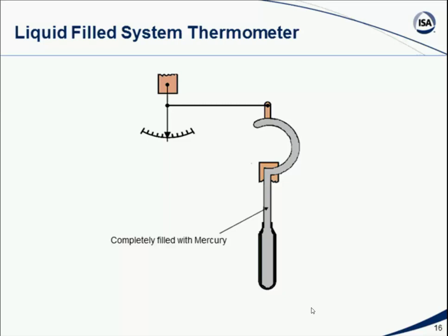Now, that C-tube design is kind of interesting because it makes use of another physical property. The metal of this pipe is consistent. It's all the same kind of metal, and therefore, when you heat a metal up, it expands. It's called the coefficient of expansion. But in this C design, what we've created here is an arc, and the outer length of the arc is longer than the inner length of the arc.